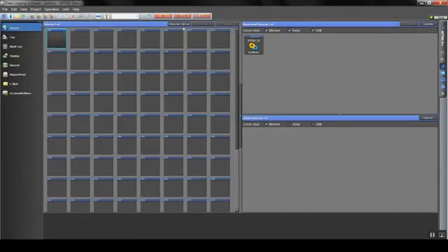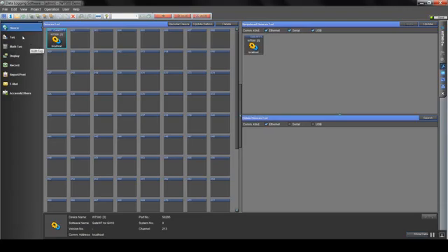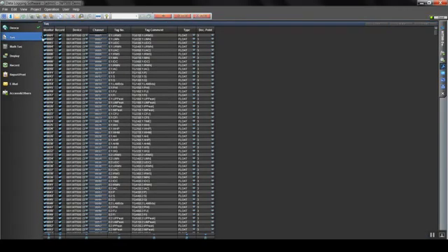I will title it WT500 Demo and select Detail Settings. Selecting Item 1, we will then register the WT500 device. Click Register Device Type and type in the entry under WT Model from the Gate WT configurator as the device name. For the host name / IP address, this will be set to localhost. Once registered, we will then go to the tag page and select the relevant tags and assign them comments.